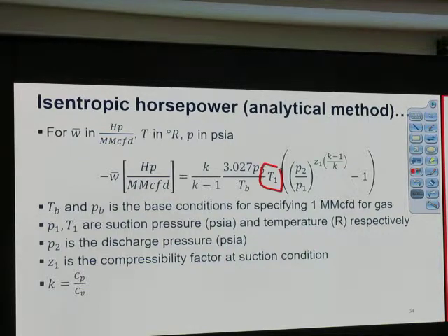So let's say the gas is cool, comes in at 80. We compress it, the temperature goes up to 250 Fahrenheit. We cool it down. When we cool it down, we may cool it down to 80 or we may cool it down to just 100. It may not be 80. So when we cool it down to 100, then the second stage, the third stage, when it cools down, it will go back to 100 again. See what I'm saying? It will repeat itself.